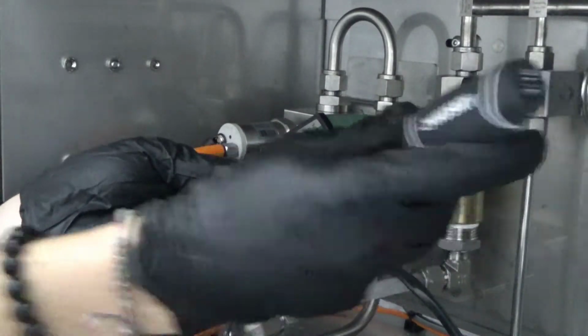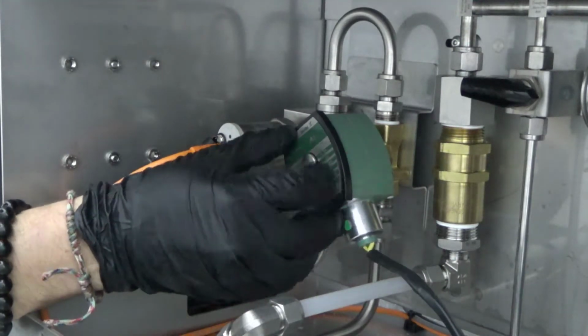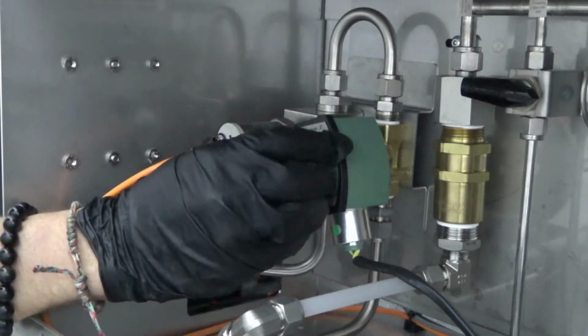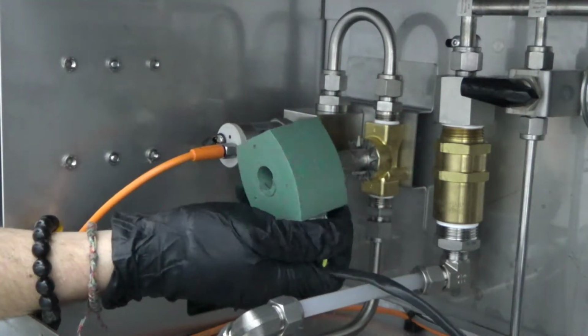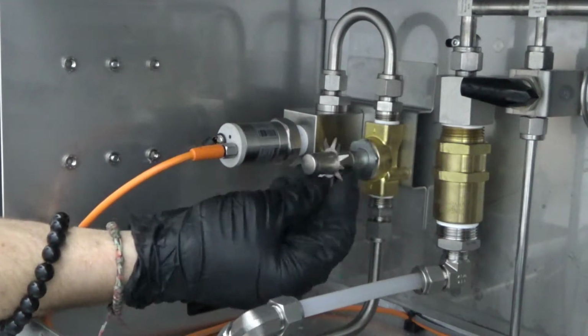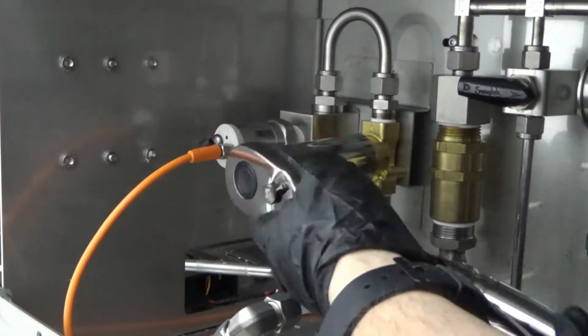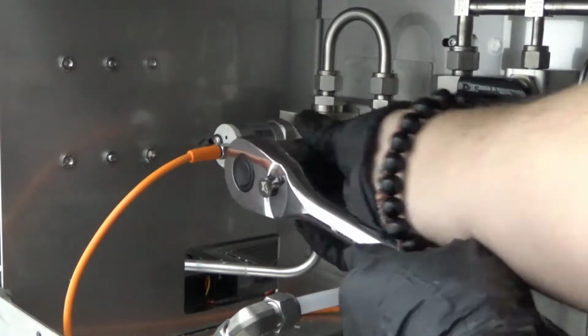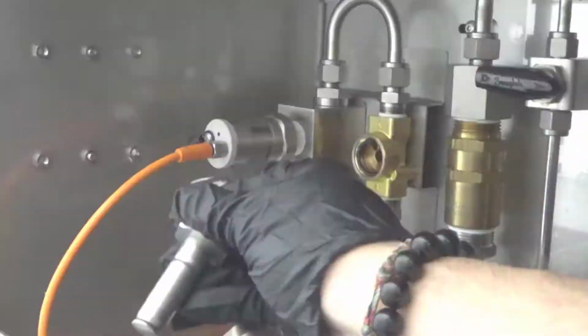We will start by prying off the red cap. Then, we will press in on the green valve coil body to allow the tool-free removal of the nameplate. We can now slide the coil body and washer off of the solenoid and set them aside for reassembly. Next, we will use our 1-inch deep socket to remove the solenoid. Take note of the orientation of components inside the solenoid for proper reassembly later.